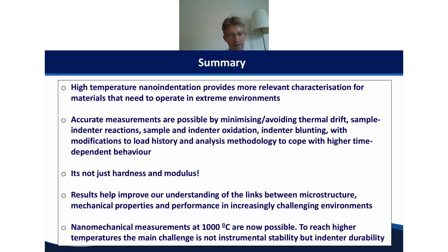I've talked a little bit about how we can have various strategies to improve measurement accuracy by minimizing or ideally avoiding thermal drift, making sure that we have inert tip-sample chemistry, eliminating sample and indenter oxidation, choosing the indenter material to avoid indenter blunting, and also to control both the loading history and the analysis methodology to allow us to effectively cope with this greater time-dependent deformation.